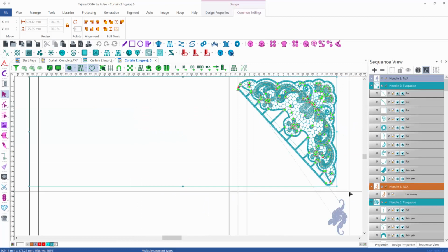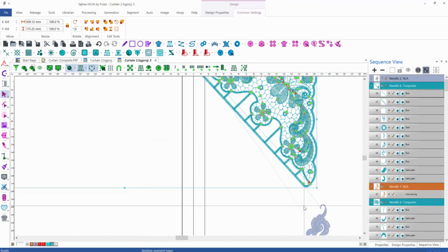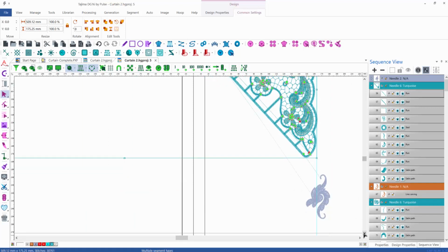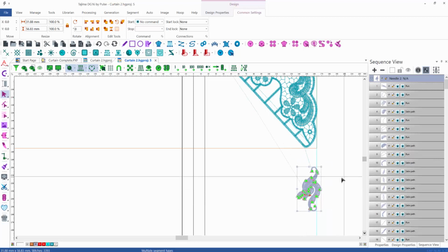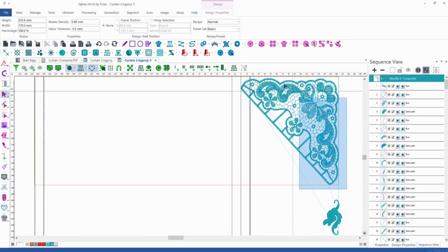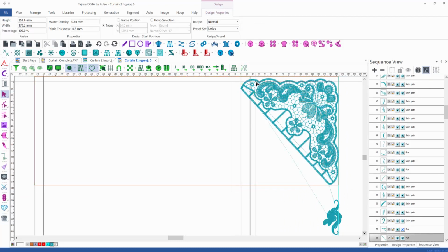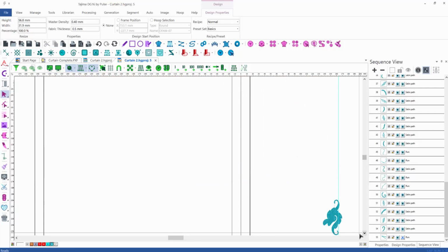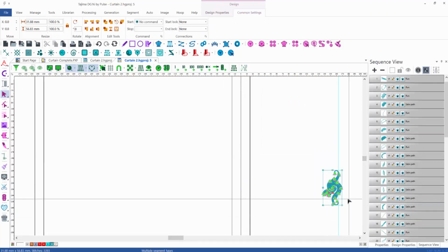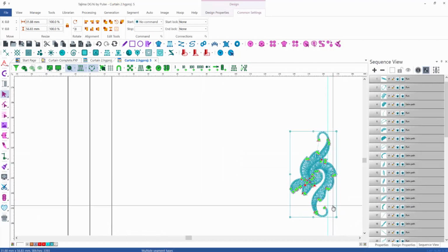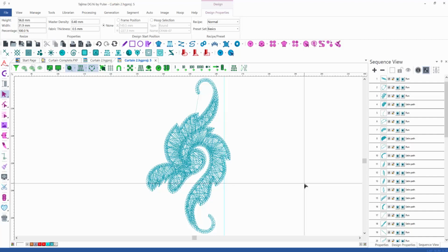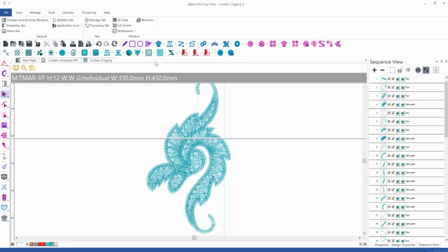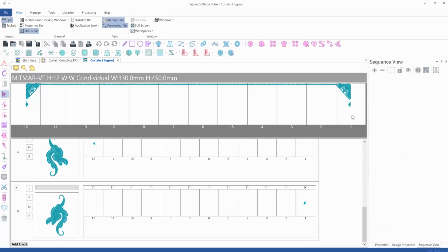Then paste what we had copied in the clipboard just before. And you can see the position of that right hand corner element with the rectangle that I drew is very good, because I can position everything now to the desired location. Change to needle number 6, and once that is done, we can now delete the parts that we don't need. Okay, so you see I'm going to move that a little bit more to the inside so it aligns to my guideline there. Looks good. Once we're done with it, Control S to save it, and we are done with our cycle number 5.